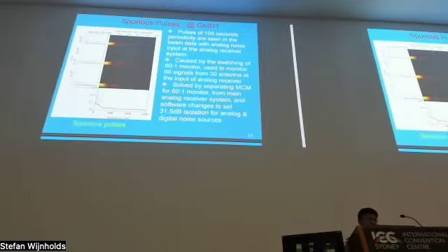So we came to know that the 60-to-1 system which we have introduced is causing these signals, pulses. So for that we have separated the 60-to-1 monitor and the main signal. They were controlled by a single monitor and control module. We have separated that MCM from the main signal, and we have made some software changes. With that, we were able to remove these pulses introduced by the 60-to-1 monitoring.